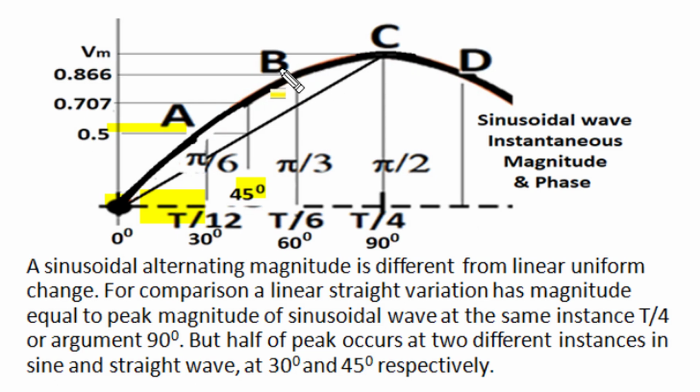But in sinusoidal variation at 45 degree we will have 70.7% value of peak magnitude. So this sinusoidal variation is fast and rapid near zero crossing, and variation got smaller rate of change near peak value. In first half 70.7% value will be obtained by sinusoidal increase, whereas in next half of this quarter only 29.3% increase will take place.